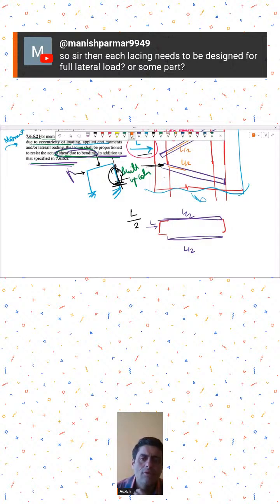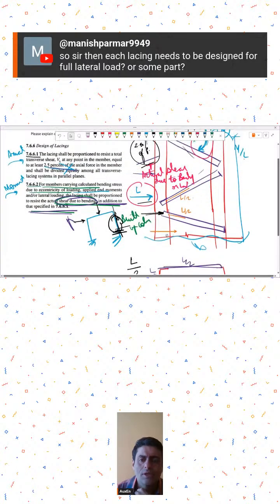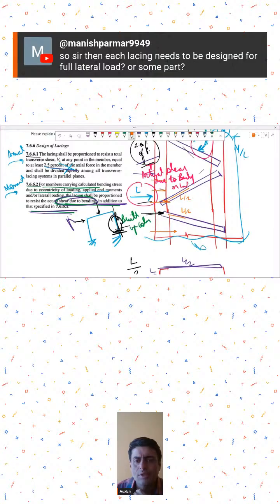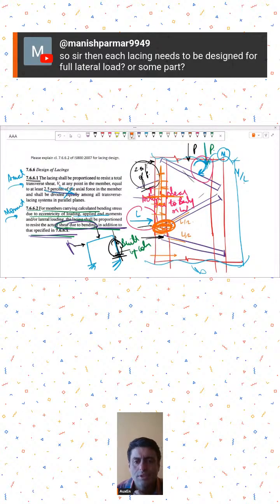That is one. If you have some shear force, then you need to convert it into the load that gets transferred to this point by some tributary width calculation. So if you have the shear over this length, you will have to find out the equivalent point load that will be acting on this.